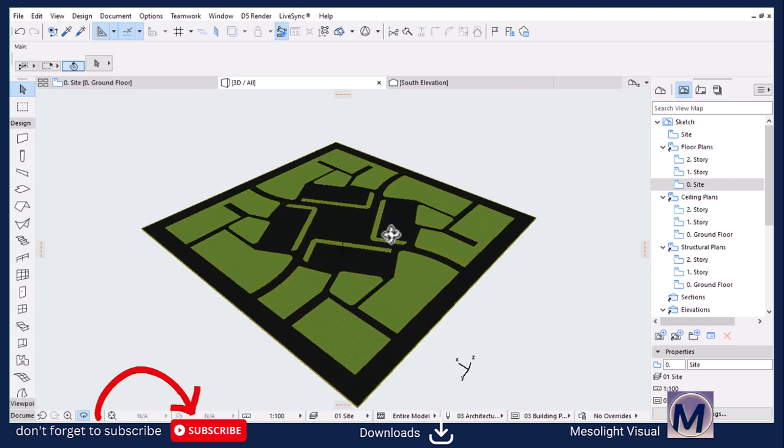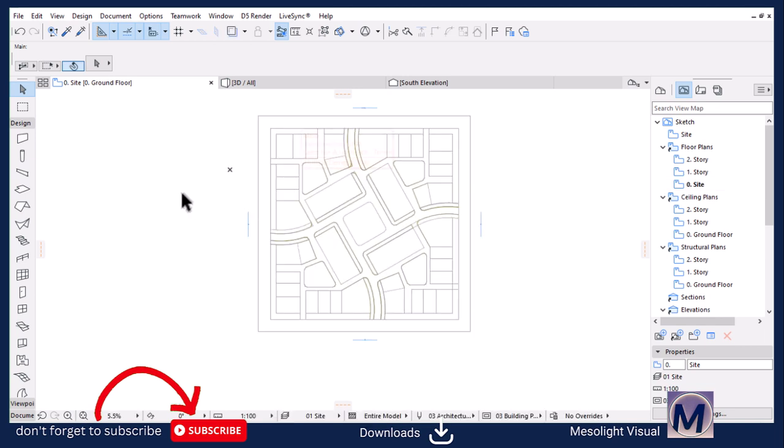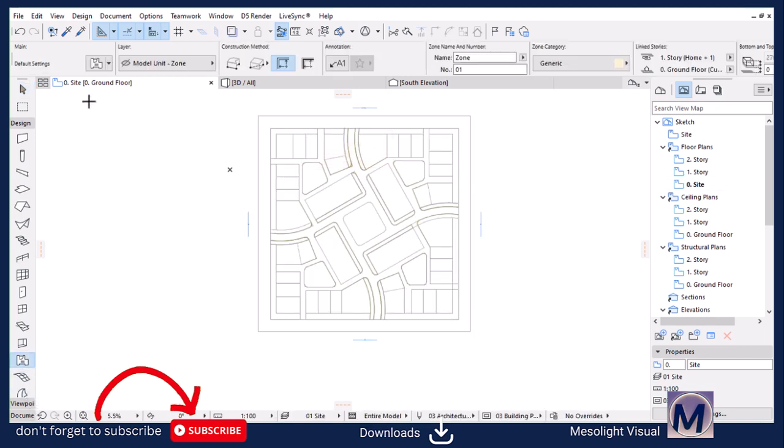I'm going to use zones. Zones are very important because you can store data and later on extract data from those. They are very parametric. So for this type of exercise, they're phenomenal in terms of achieving great results. So I'm going to activate the zone tool, and then we have to differentiate our zones because we have residential and the commercial part.